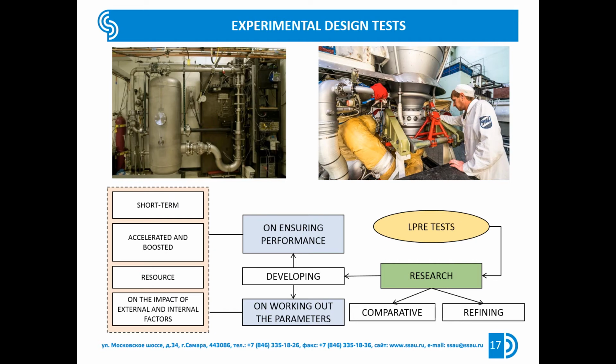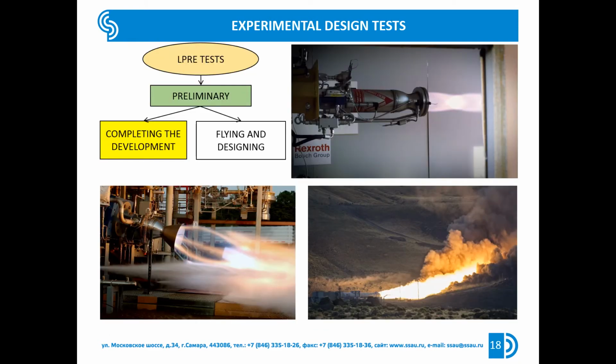After the developmental testing phase, of which the developmental testing is the main part, the pre-testing phase commences. During the pre-testing phase, final development and flight tests are conducted. The purpose of the final development tests is to confirm that the performance of the liquid propellant rocket engine, including its reliability, complies with the technical specification and to evaluate the possibility of submitting it for acceptance testing. The basic material for assessing reliability is the result of final inspection tests. Tests similar to final refinement tests are sometimes also called qualifications.